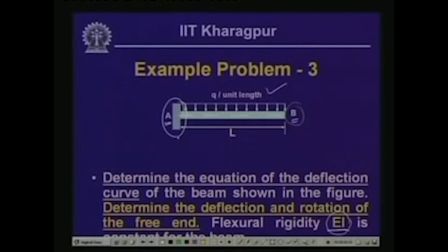At this fixed end, you will have the vertical force, let us call this RA, the horizontal reactive force, let us call this HA, and the bending moment M. If we take the horizontal, vertical and moment equilibrium, summation of horizontal forces equals 0 will give HA equals 0. Summation of vertical forces equals 0 will give RA, acting vertically upwards, minus q times L, equals 0.